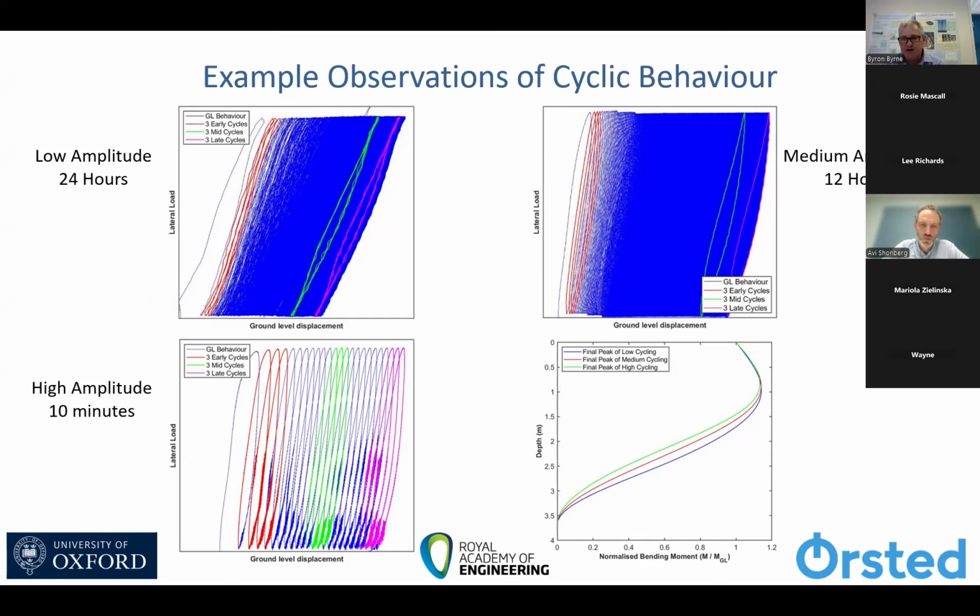All of this behavior is very consistent test to test, and also very consistent with work observed in the laboratory. And we can see quite clearly that perhaps the ratcheting is a function of the load level. And with this data, we can also track the stiffness and its evolution through the different loadings.